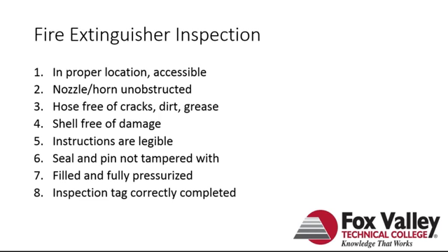The seal and the pin aren't tampered with. We have all kinds of pictures, stuff like that. People using zip ties to hold the pin in place. Well, okay, yeah, the pin's going to stay there. Fortunately, even when you need it, it's going to stay there as well. Is it filled and fully pressurized? And is the inspection tag correctly completed? You want to make sure all of these are done when you're doing your inspections on your fire extinguishers.